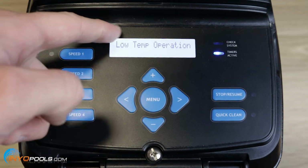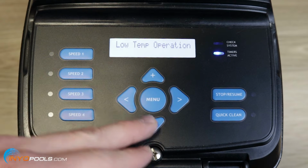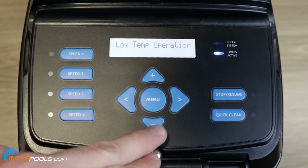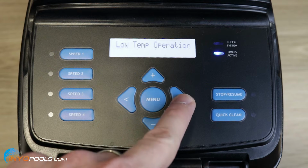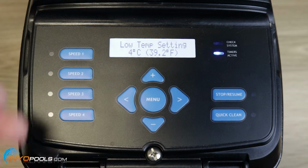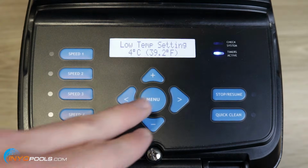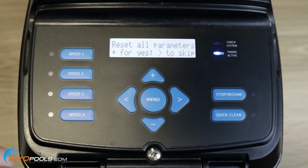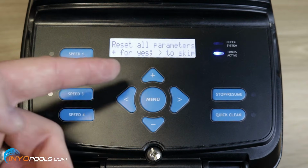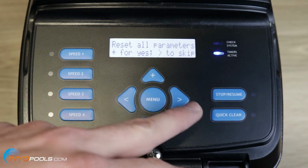All right, the next screen is low temp operation. It's currently disabled. Basically, if you're expecting it to freeze, or if it gets down to 35 degrees, you'd want your pump to turn on. So if you want that feature, you would just hit the down arrow, change it to enabled, and hit over. Okay, and then the next screen would have a low temp setting. This is basically when you'd want the pump to turn on. So currently it'd be turning on at 39 degrees Fahrenheit. Reset all parameters. If you ever want to reset your schedule, you would just hit plus for yes.